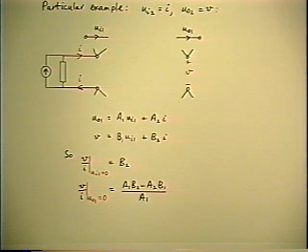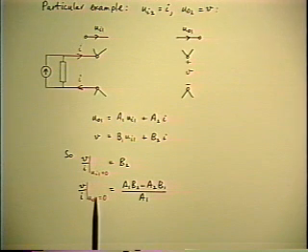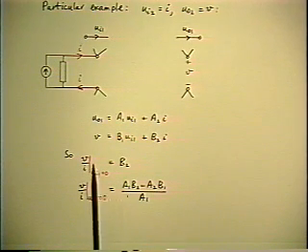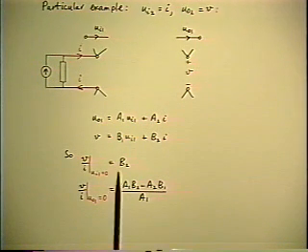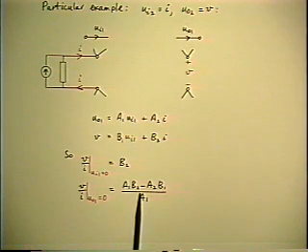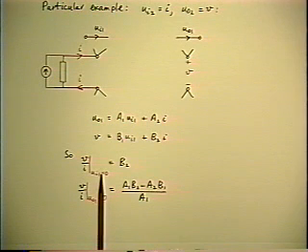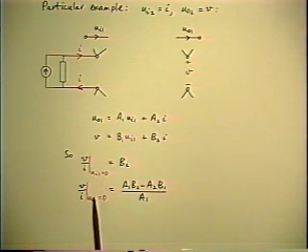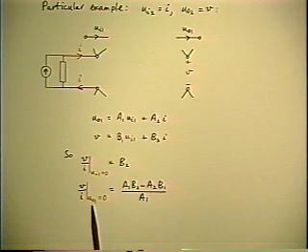They're the same transfer function. The question was that they're not the same quantity. Well, in one sense they are. It's the ratio of the same two quantities, the same transfer function. What is different is you get two different answers, because the physical conditions are different. Well, because the other input is different. In one case there isn't any other input. In the second case there is another input, and it has a specific value, namely the one that nulls the other output. That's the hidden input.